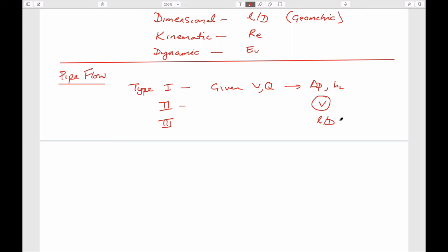And that's typically the most difficult because you have to iterate. Given a desired flow rate and a pressure drop, you have to figure out exactly what the magnitudes of the pipes are by making a first guess and then moving towards it. So probably these latter two we wouldn't care too much about, but they would be closer to type 1 systems or some variants on those.